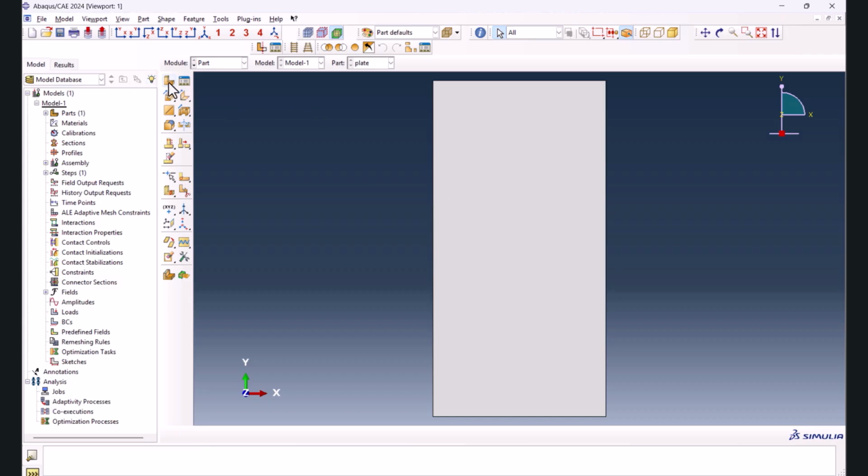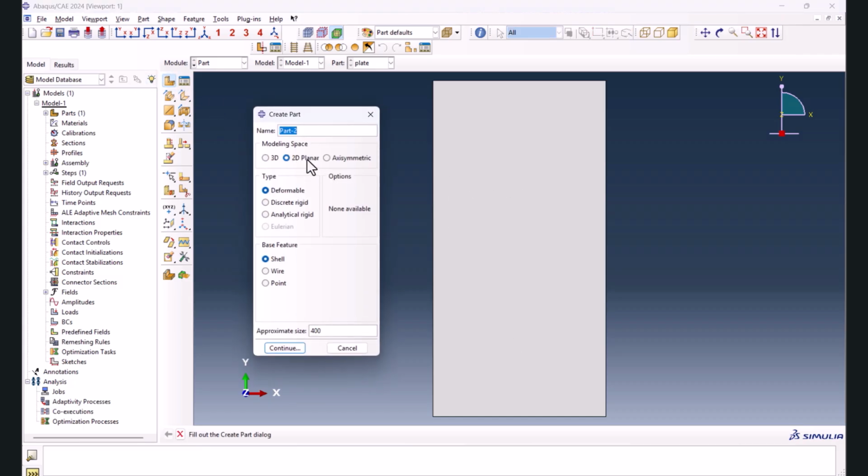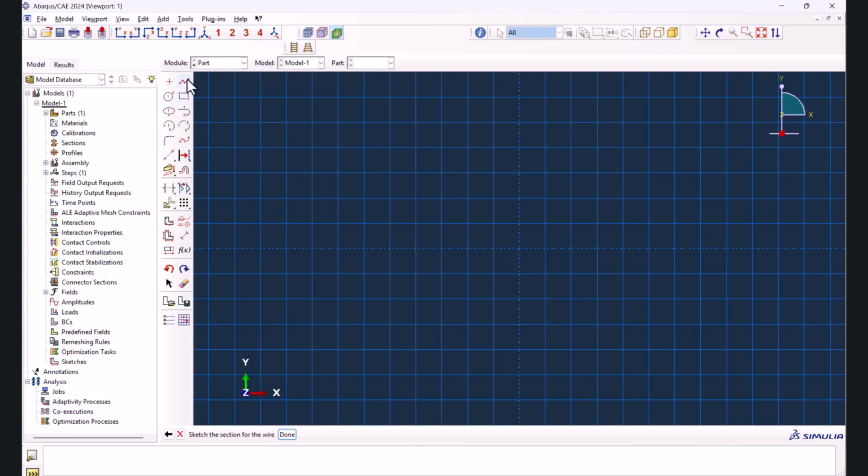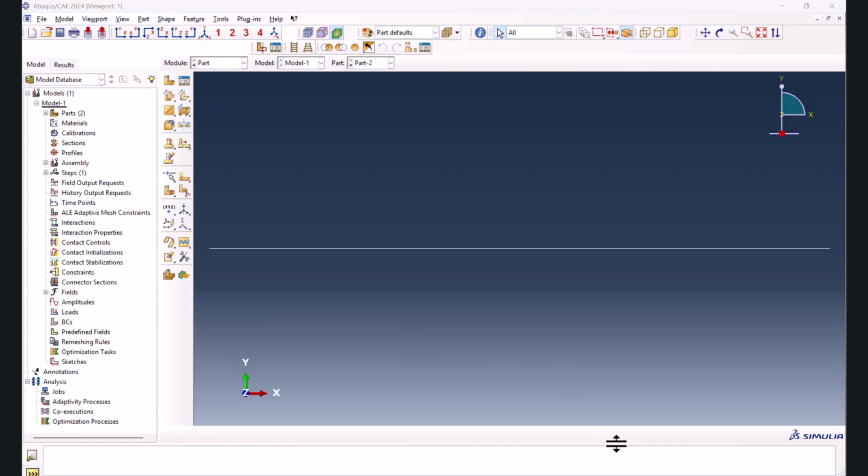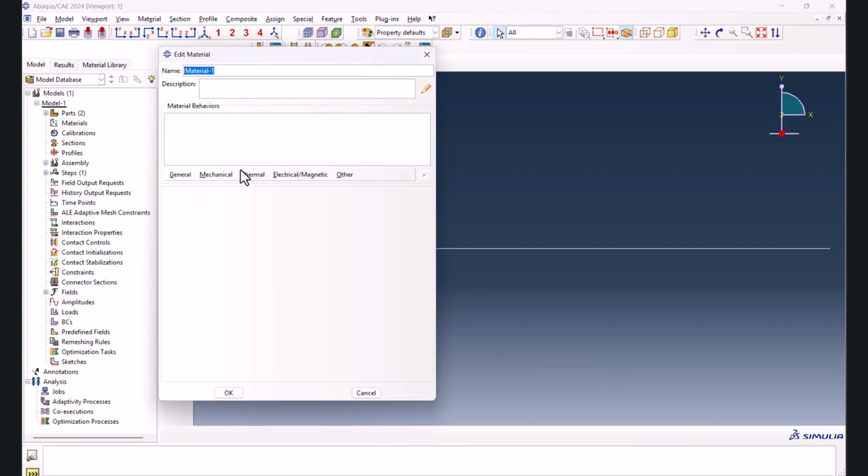Now let's create the crack. So from 2D, you would put this on wire and we create just a simple line. We assume the crack to be 20 millimeters. Then we have the crack. Now that we have the geometry, let's move to defining materials properties.